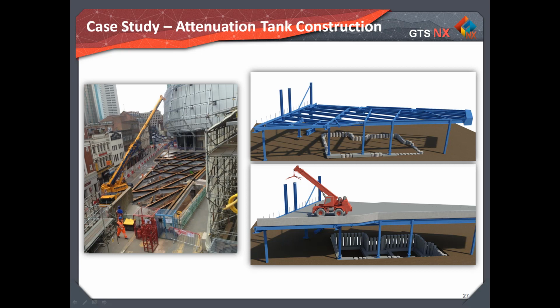However, in temporary conditions, that is during excavation to form the tank, the wall acts as a cantilever, for which any excessive deflection would have impacted the structural steelwork already installed and supported by a number of contiguous piles. The photo on the left shows the steelwork which had to be installed prior to any excavation. The ones on the right are the 3D models of the steelwork and attenuation tank below.